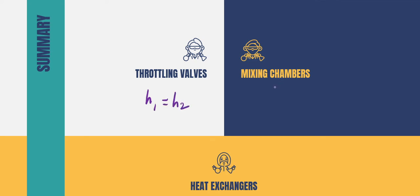Mixing chamber: your kinetic energy and potential energy are all equal to 0, and your equation is left with only M and H, and there is no work done, and Q equals 0. This is the common knowledge, but you also need to double confirm with the question. Sometimes they say there is a heat loss, so Q is not equal to 0. So it depends.